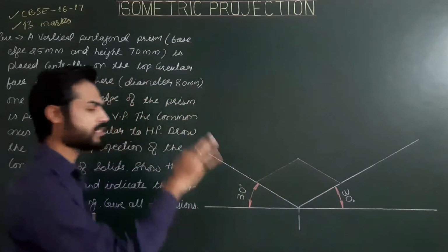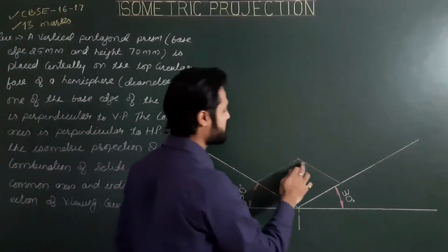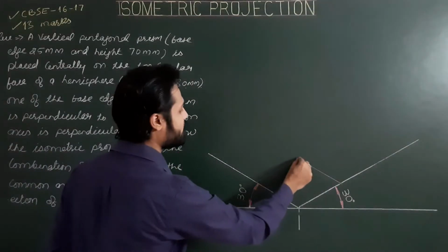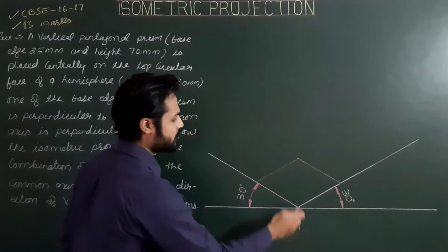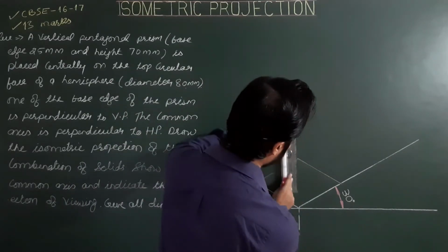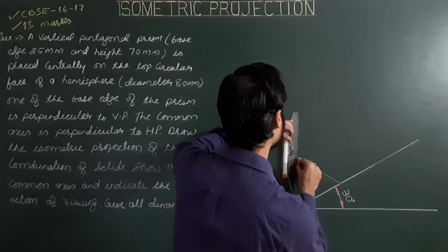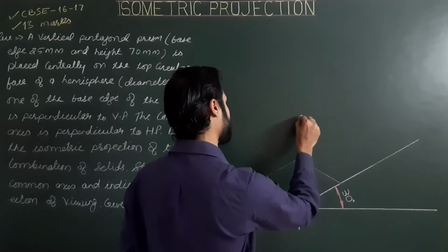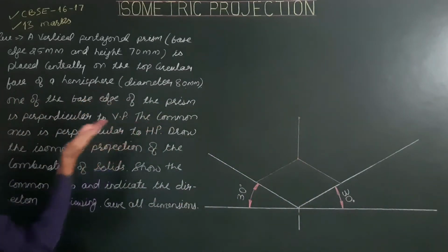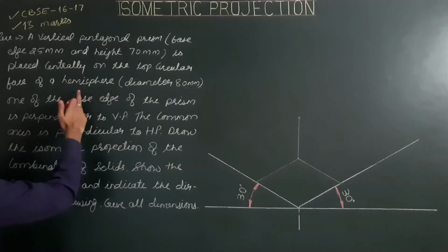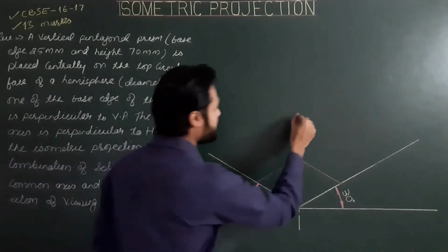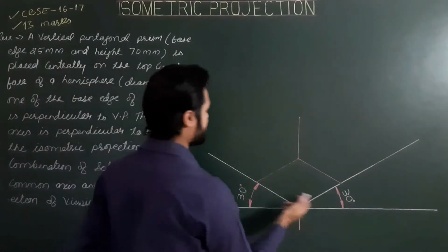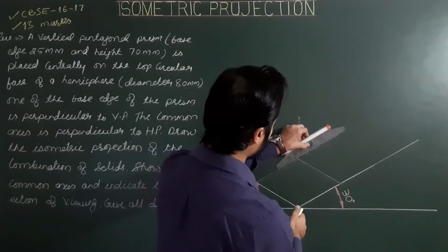This point is the center of the projected square, or simply the point of contact of the curved portion of the hemisphere and the ground. Now from this point, we have to draw a line parallel to the third or vertical axis, again for a length of iso 40. Now this point is the center of the top circular plane or circular face of the hemisphere. Now from this point, drawing lines parallel to the first and second iso-axis.